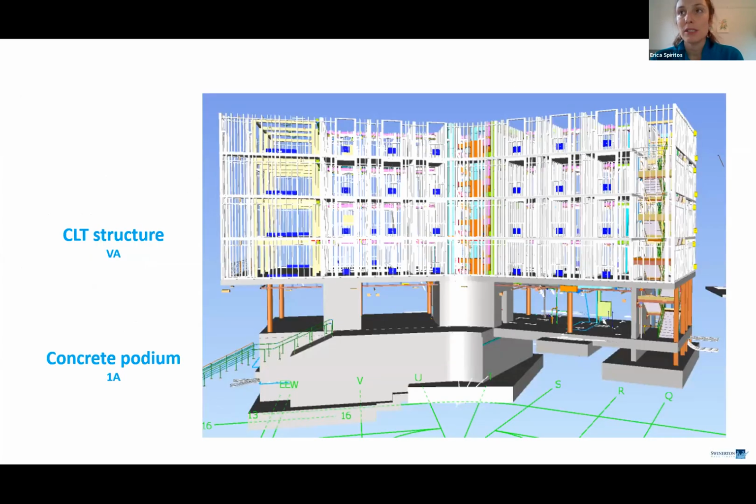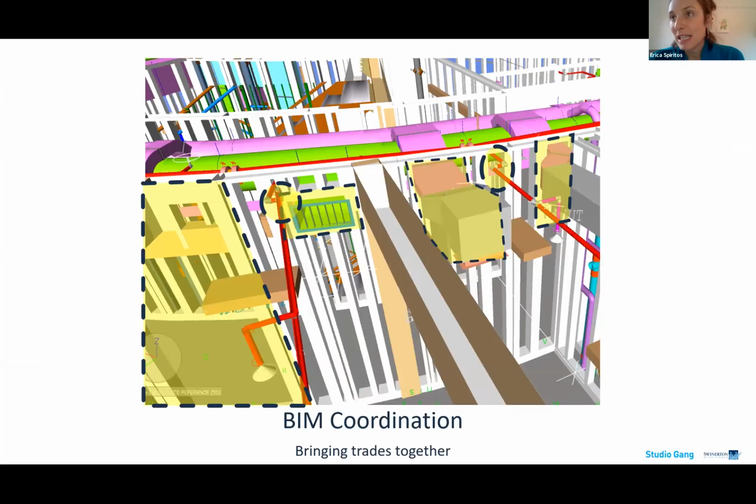And then from there, we're building 3D models that take into account the structure and then any material that the structure might interface with. So that might be concrete slab, it might be concrete cores, it might be steel brace frames. In this case, we're looking at all of the fire sprinkler pipe, we're looking at ducts, we're looking at plumbing, and thinking about how that all routes through prefabricated stud walls and then penetrates up through CLT floor decks. Making sure that there's no clash with the hold downs at the base of the wall, or making sure that the walls don't cover up penetrations, for example.